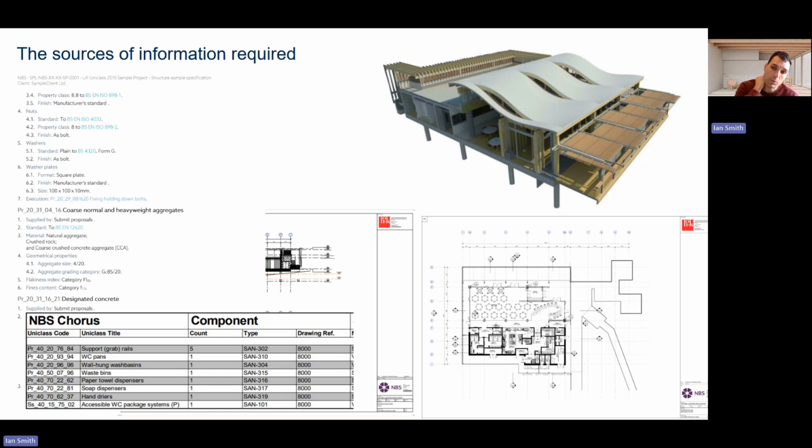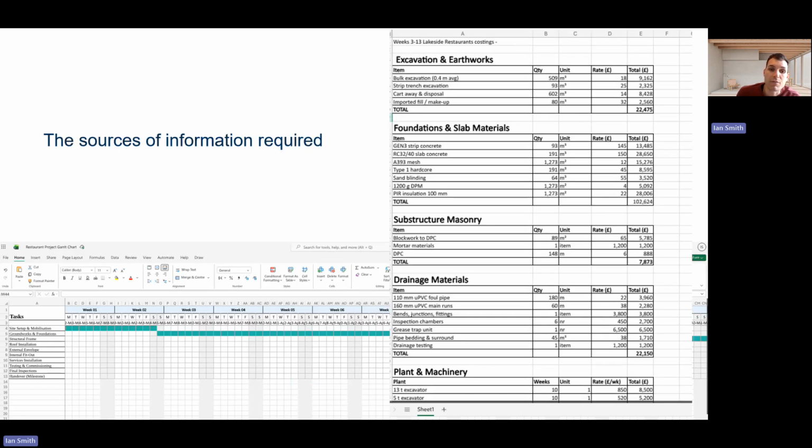So compare it with traditional drawings, like we can see on the screen. BIM drawings provide a higher level of coordination and help to reduce errors before construction begins, and will support me as a construction supervisor to ensure that the finished product is as it should be. They can also help with CDM regulations, as we can identify design risks earlier on.